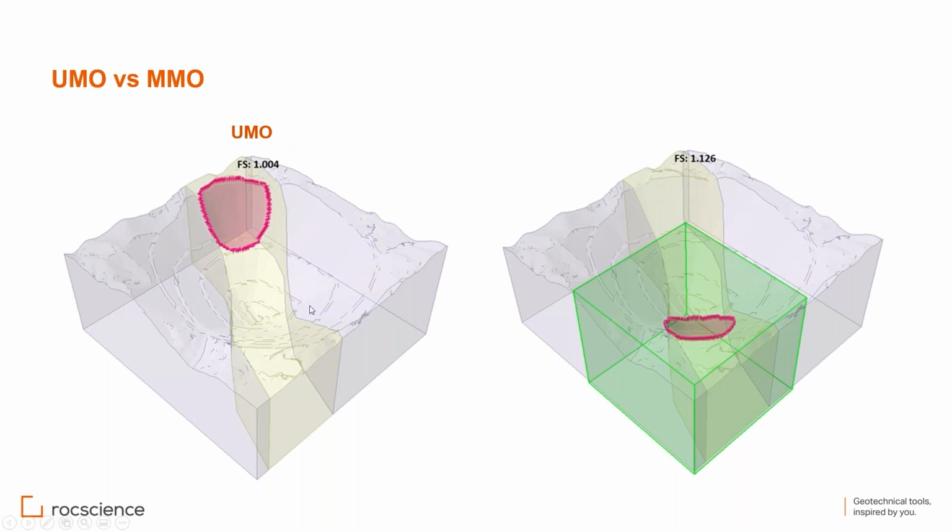So for this open pit, which is kind of symmetrical, you see there is a slip surface here, and you can expect there is a lower factor of safety on the other side of the pit as well. To get that one, you have to define a focus search, a search limit for that specific region, to give you the critical slip surface.